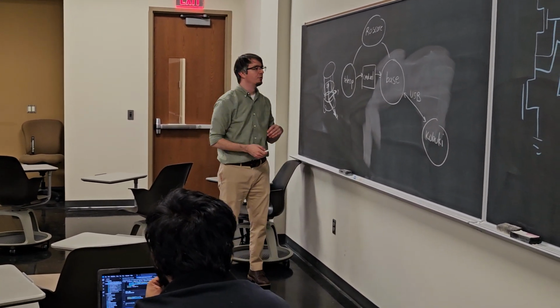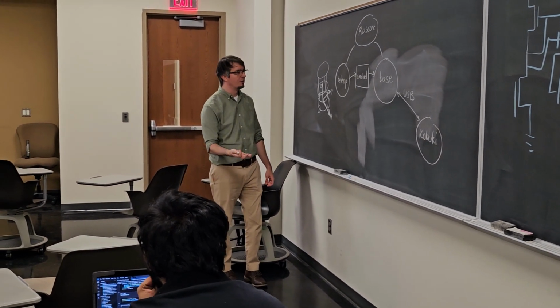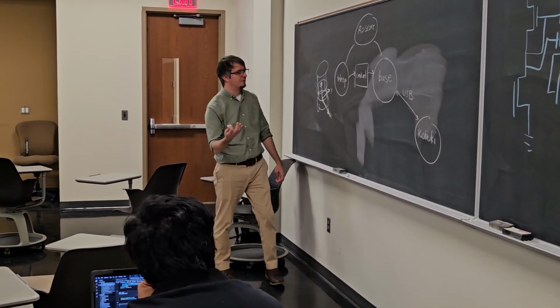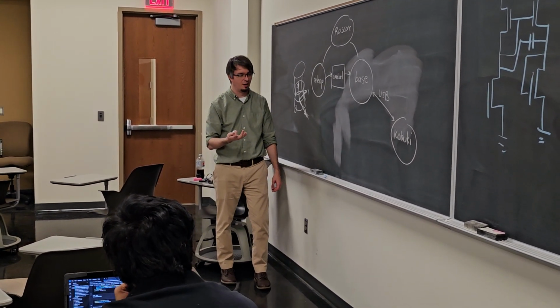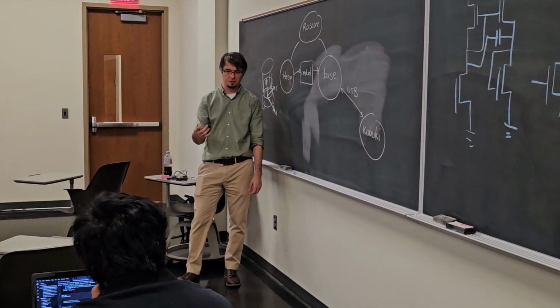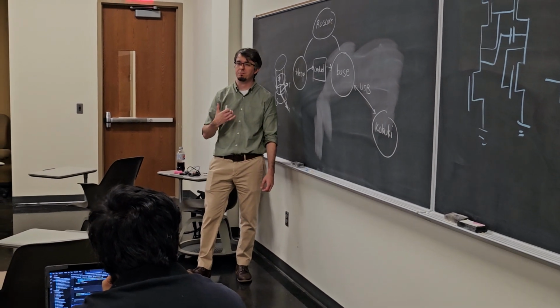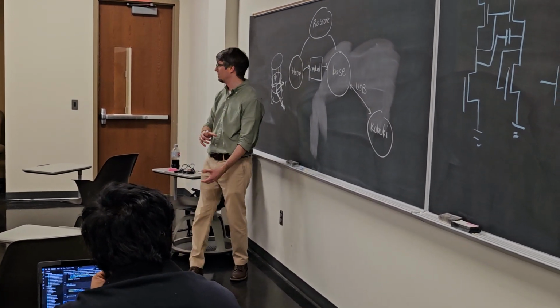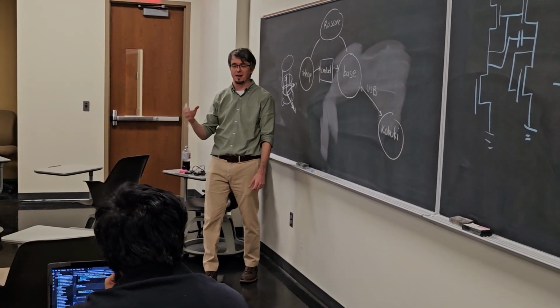But basically the messaging is facilitated by the ROS core. In C++ and Python, which are the two main languages used in ROS, they provide APIs that you can call to publish the messages. And they also have structures that already exist, like if I want to publish a twist command, there's a structure I can populate that has those